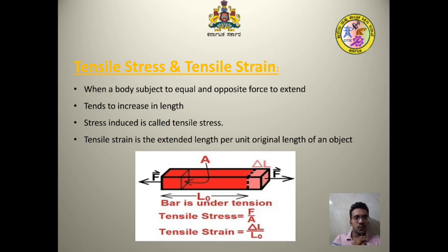Because whenever the force has been applied, depending upon the tensile force, the tensile stress will be created as well as tensile strain will be created. This tensile force is the pulling force. It is not a pushing force. The pulling force will be applied at both the ends.